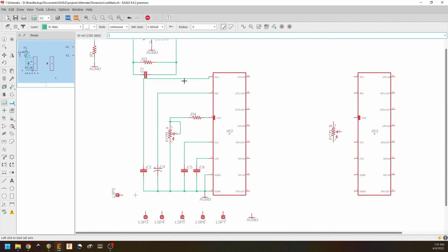So that is it for this side of the chip. Now we move on to the other side of the chip, where we have 2 op amps that are set up for filtering of our modulator and demodulator. Our actual delay output is going to come off of pin 12. We're going to use this op amp on pins 15 and 16 as our input filtering, and this op amp for filtering our output.